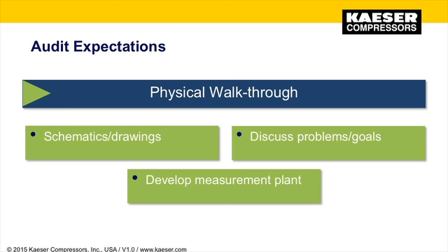Consider that some poorly performing compressed air systems can be improved immediately. If the compressed air auditor determines that piping within the compressor room is just too small to accommodate the prevailing demand, or the lack of a master controller is constantly requiring multiple compressors to load when only one is necessary, these items can be addressed prior to completing an audit. However, typically, upper management requires details on savings potentials, and in those cases, an air audit should be completed first to provide such savings potentials, and subsequent audits be completed as necessary to show those improvements in the system.